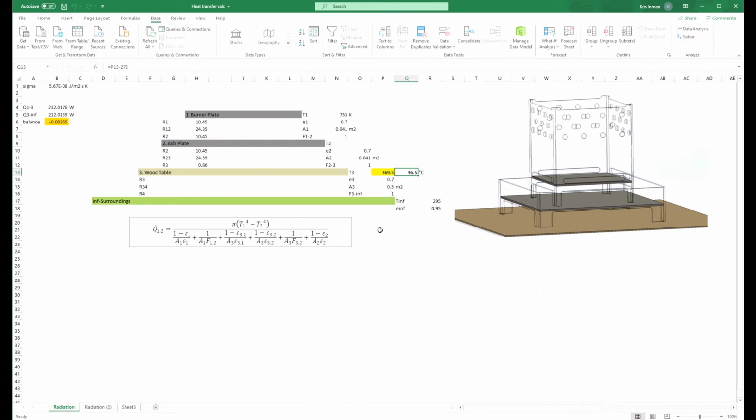What's interesting is that if you look at these equations and break everything down, you can see that every time you add a heat shield like this to something, it cuts your heat transfer rate in half. This is the same reason catalytic converters have these very thin sheet metal shields on them: it does a surprisingly good job of insulating them from the outside environment and not setting stuff on fire when you drive over it.